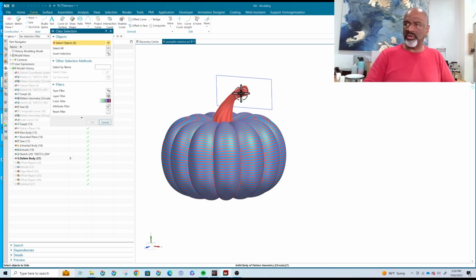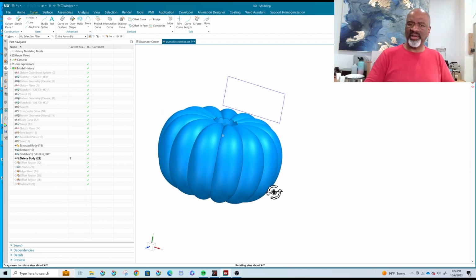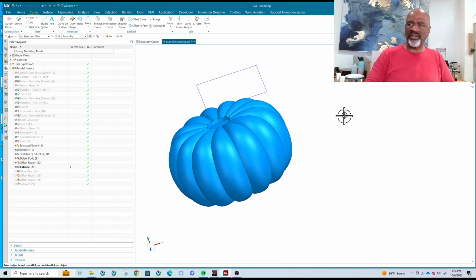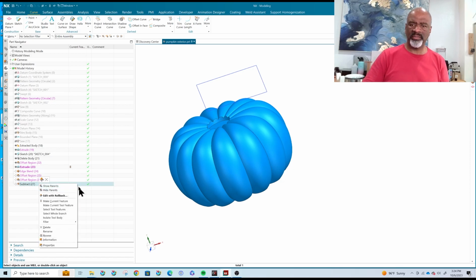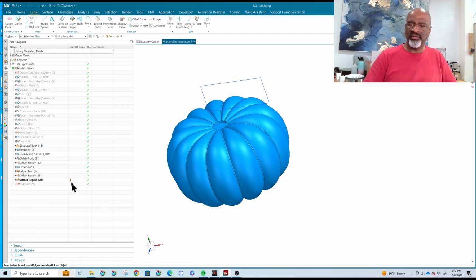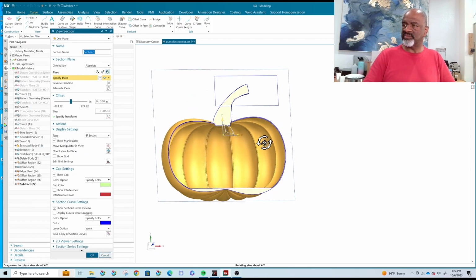Control B. So what I did was I made an interior model. See the interior model? And then with the interior model, I offset it and I cut it down. I offset it with a negative offset, so this skin is forced inward. And then I did a subtract. And finally I had this, just like that.